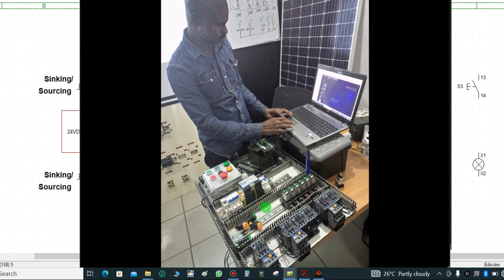Although we used to interface a control panel with your control room, that is, the control room is where you monitor the activities of your PLC operation. Then they used to have a central control panel that your PLC will communicate to. And that particular control panel will finally deliver the instruction from the PLC to the field instrument. So that particular central control panel is what this one represents. This represents your panel that will communicate to your field instrument through PLC instruction.